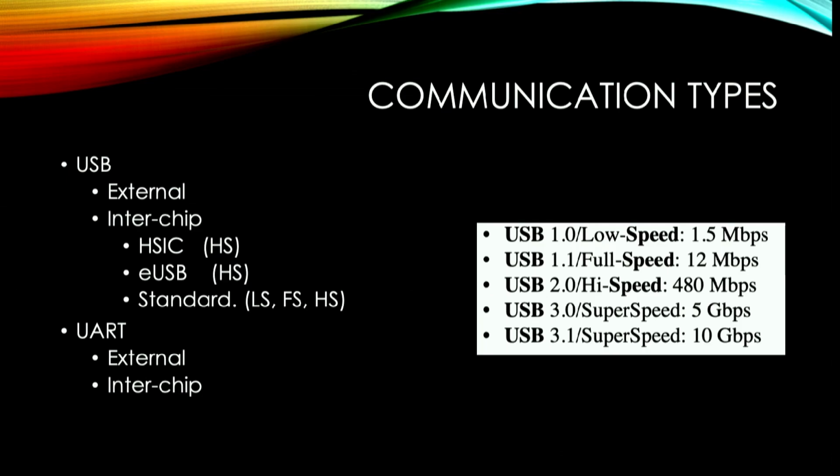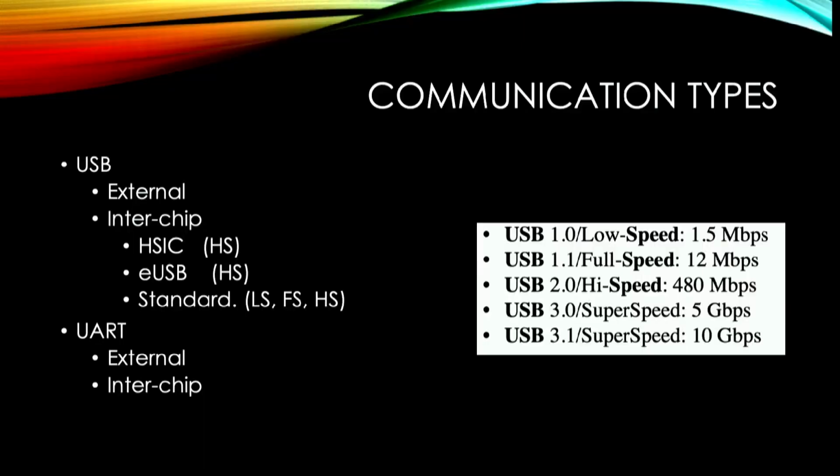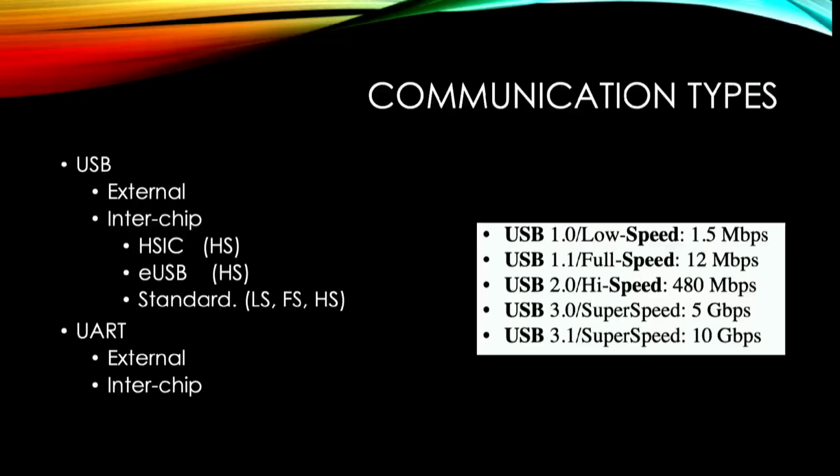I've seen this used on communications to solid-state drives on certain embedded devices, where the solid-state drive was on another board or another system. That was the first time I came across eUSB. And then you have standard, which is low speed, full speed, and high speed. The super speeds, I've yet to see on an IoT device. There's rarely a reason for it.